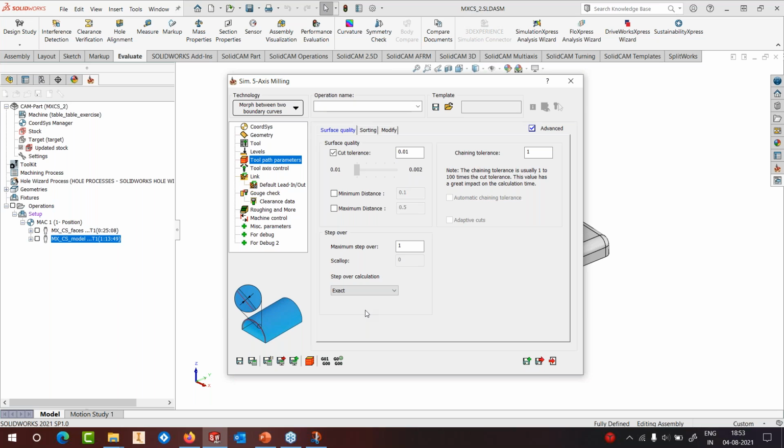But for 5-axis, yes, if you're wanting to machine the entire model, then you need the geodesic, because here we don't support the entire model. We support infinite surfaces. Those surfaces will have to be picked by the user. Whereas with geodesic, you have that option of either picking infinite surfaces or picking the entire model as one full solid and allowing it to machine.